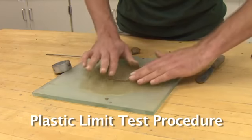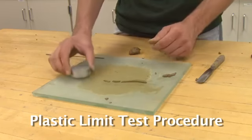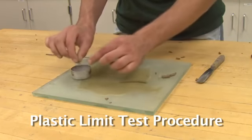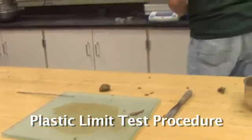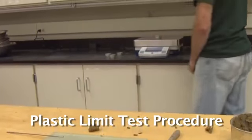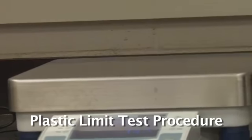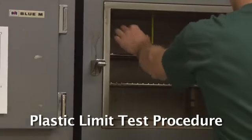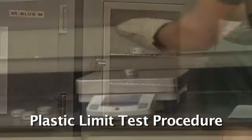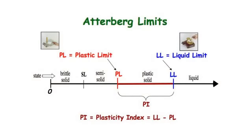Once the soil crumbles at 3 millimeters, collect samples of the crumbling soil and place them in pre-weighed tare cans for moisture content determination. Repeat the test enough times so that enough soil has been obtained for 2 moisture content samples of approximately 6 grams each. Record the wet weights of the moisture content samples and place them in the oven. Reweigh the samples again in 24 hours. The average of the 2 moisture contents is the plastic limit.